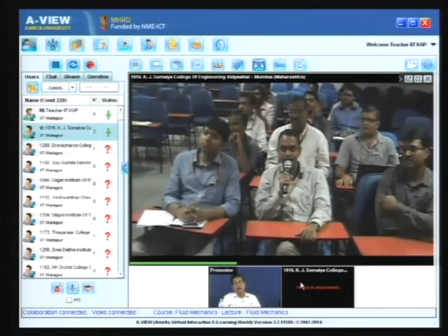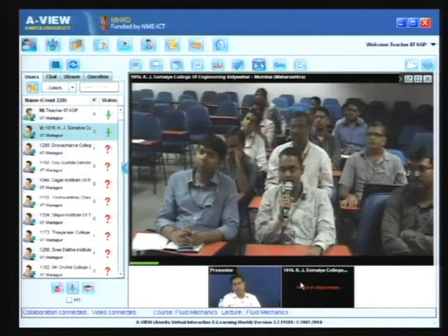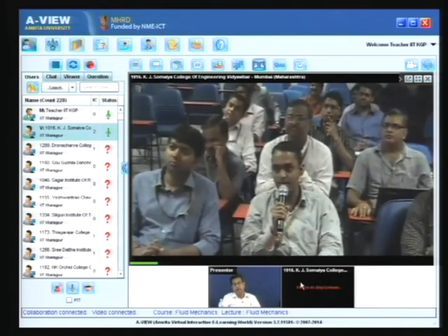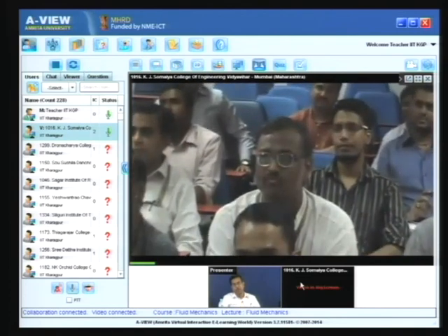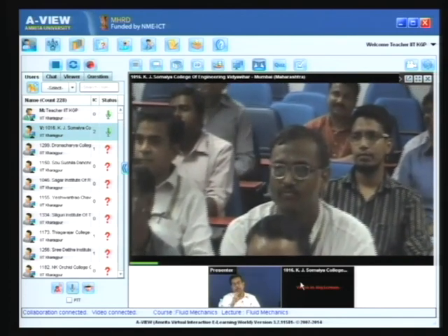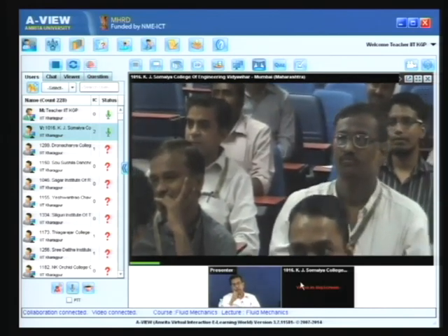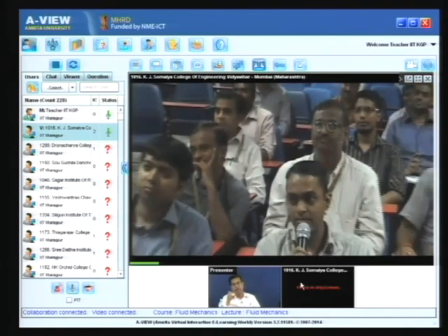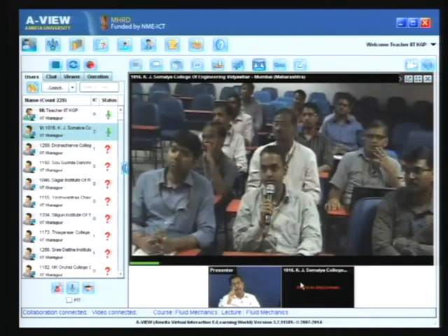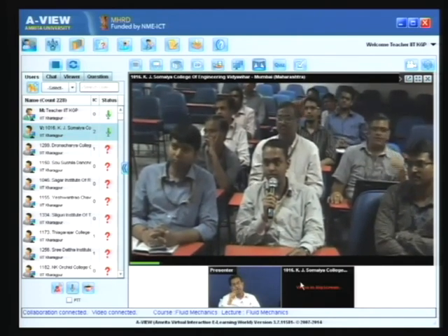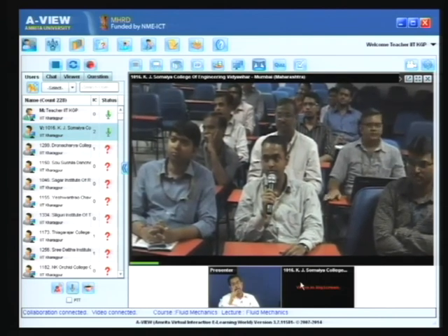Now, while we calculate the blade efficiency of a Pelton turbine, not the hydraulic efficiency, blade efficiency or hydraulic efficiency of the wheel, then definitely the kinetic energy at the inlet is the input energy. Then we will find out the work head developed by the wheel of the Pelton turbine, which is (Vw1 U1 minus Vw2 U2) by g, and the inlet energy, the kinetic energy, is the energy inlet to the blade. So, this is the blade efficiency, usually termed as blade efficiency or hydraulic efficiency of the blade.